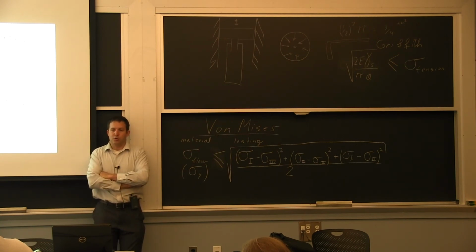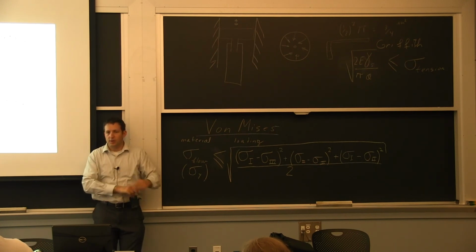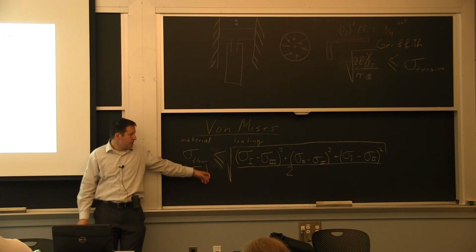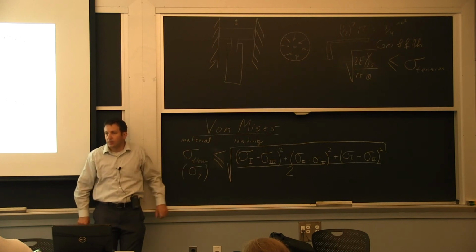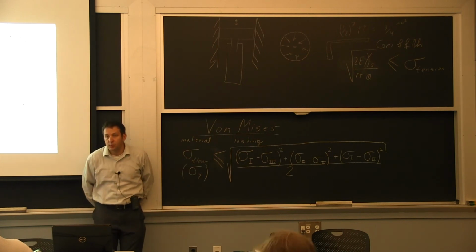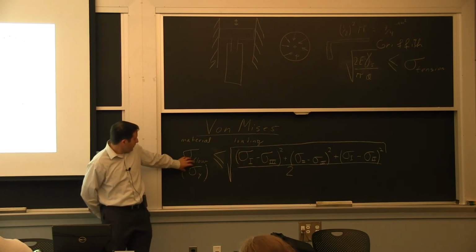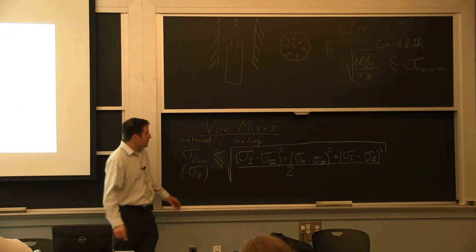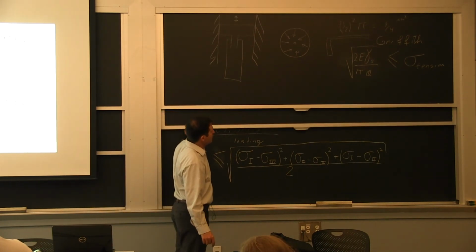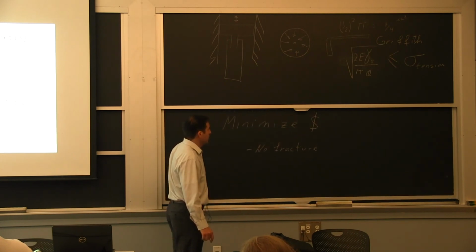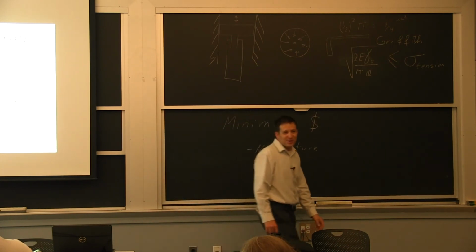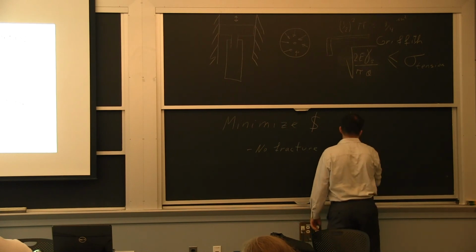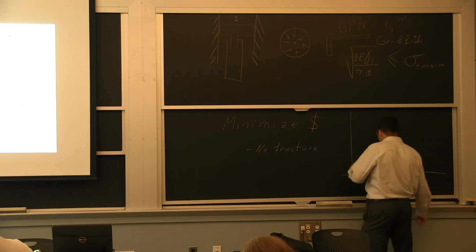At colder temperature, you don't completely stop the deformation. If you were able to deform the material in compression even at cold temperature, this still works. You still have flow of material, but it requires more stress. The value here of the flow stress is going way up as you decrease the temperature. And that's, to me, the best way for you in hopefully 5-10 years, maybe 20, to remember this, even if you don't work in the area of material properties.